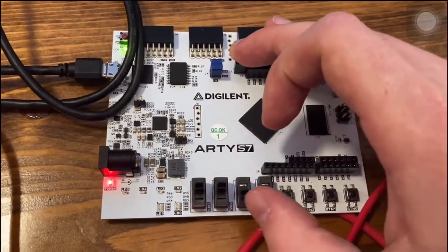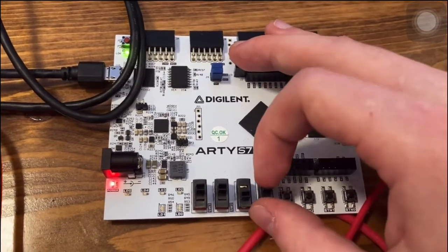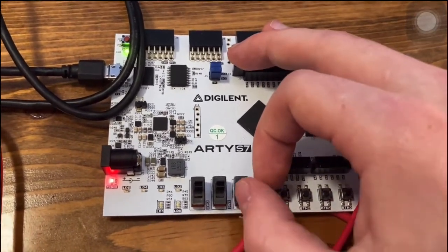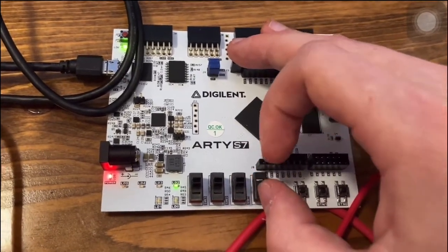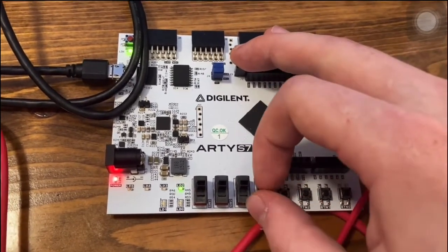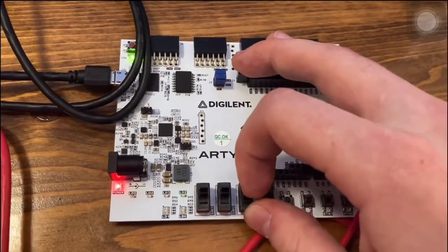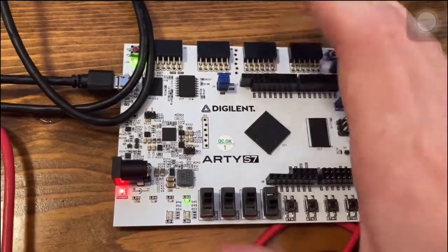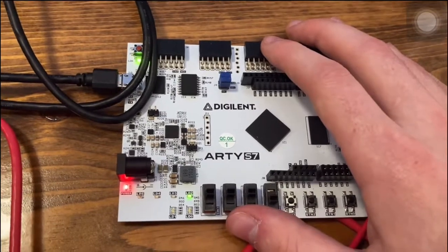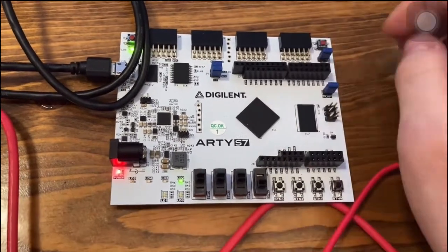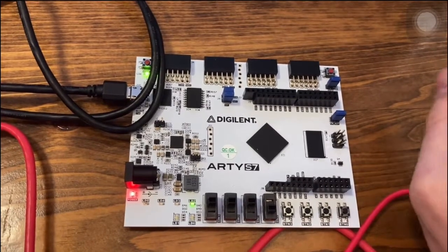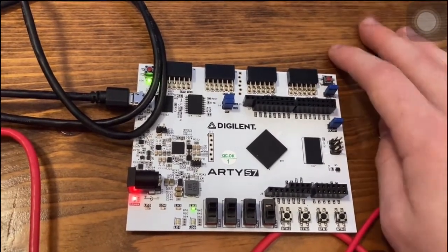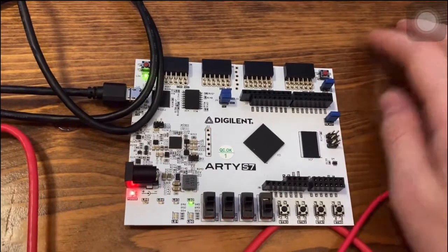So right now I've got in 0, 0, not going to do anything. 0, 1, not going to do anything. 1, 0, we see that LED 2 has gone high. But 1, 1, and it goes back low. So we are correctly detecting 1, 0 on our LED. So yeah, there we go. We've got this FSM fully written in VHDL, simulated, and working on the board. Thanks.